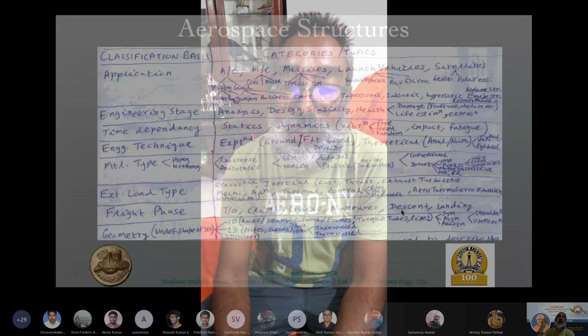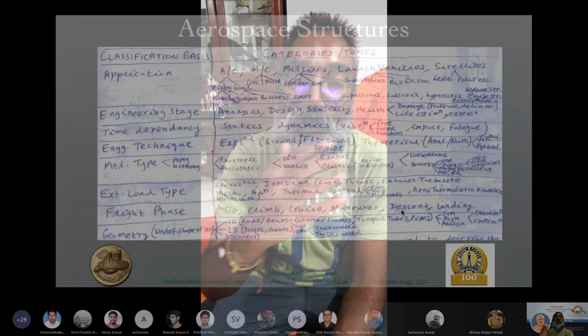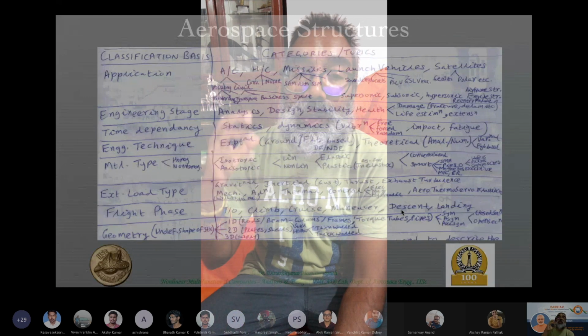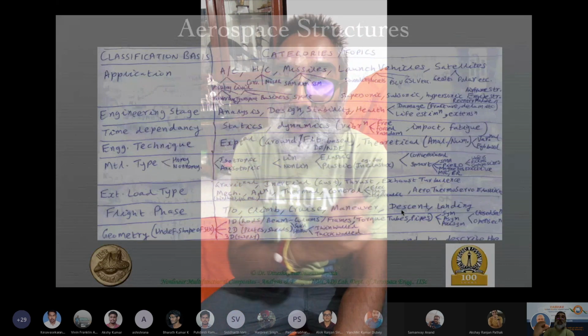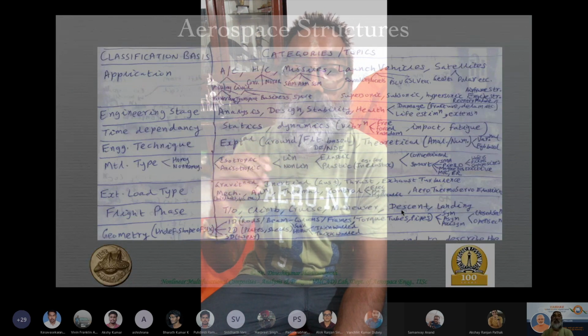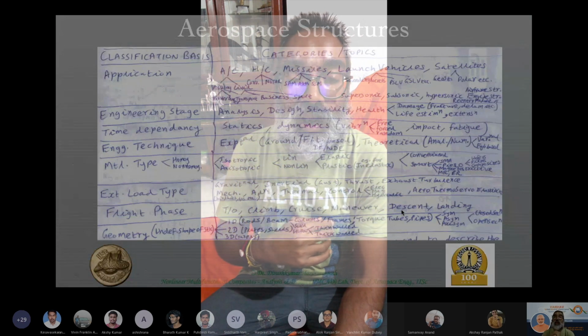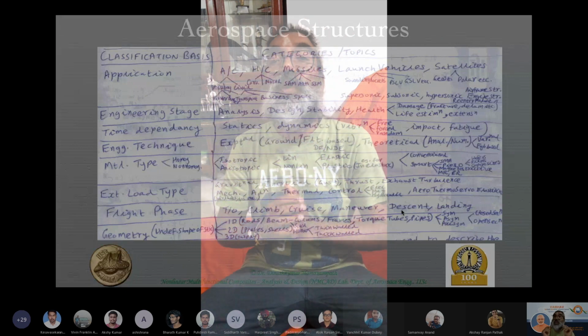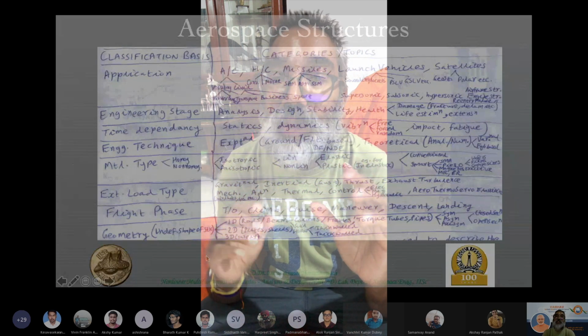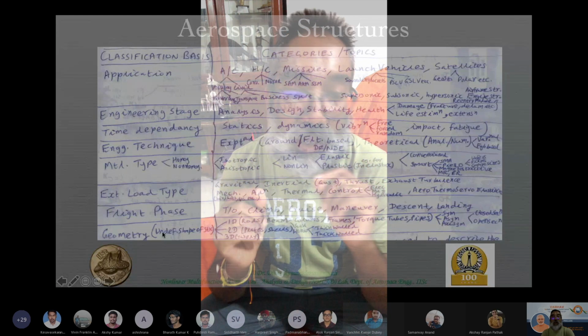So we need to consider all of these phases that an aircraft would typically operate in and take the most critical phase for a particular component and make sure that the material choices that we make, it could be multiple materials, all the material choices, the geometric choices, the joint choices that we make between multiple components, will be able to handle that most critical phase of the flight.